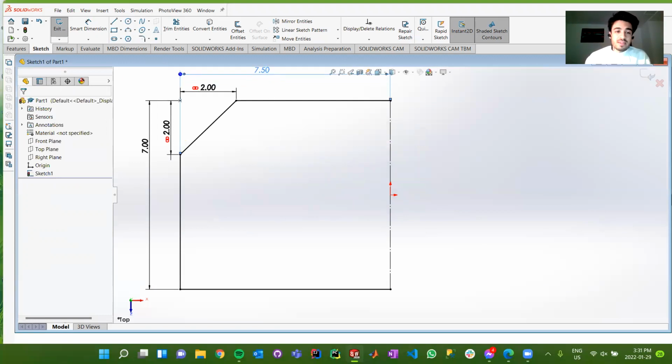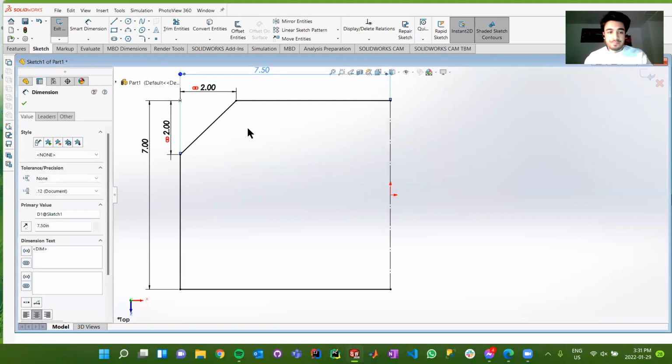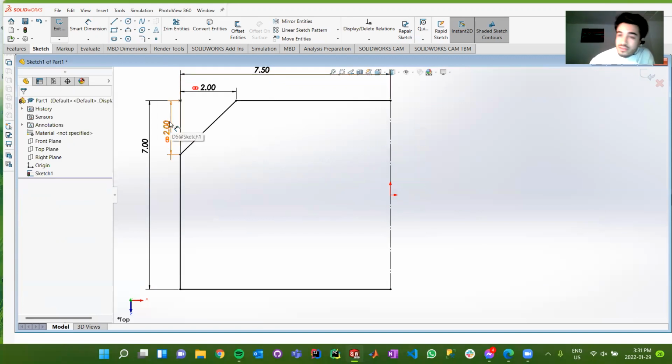You'll see with this sketch chamfer I put in, essentially that 2 inches that I specified, think of it like this. So we selected an equal spacing chamfer, meaning that essentially the height of the chamfer and the length or the width of the chamfer, or that we could call it the base, are equidistant when it comes to how much space they occupy. So they're both 2 inches wide, right?